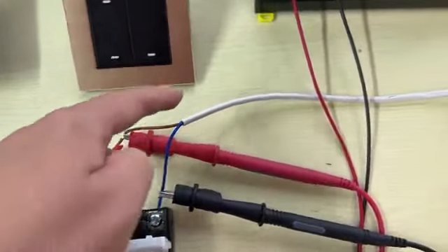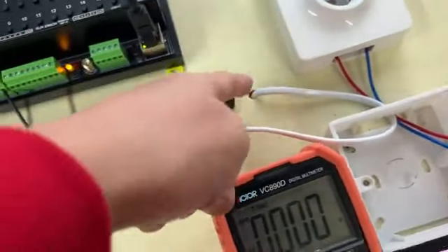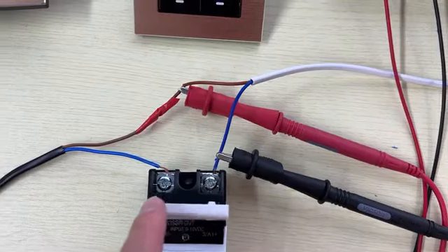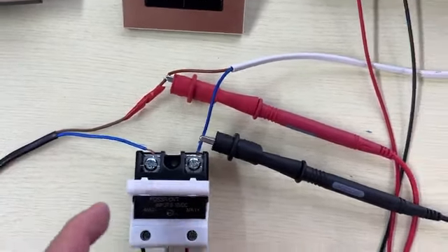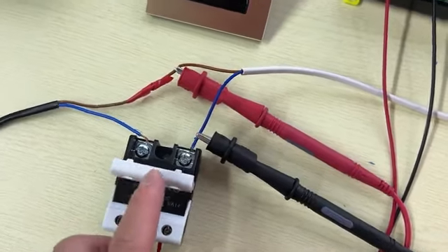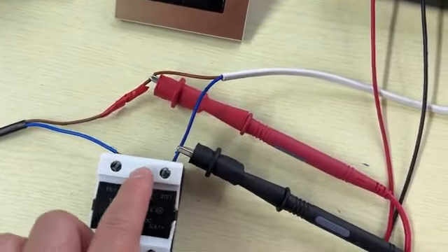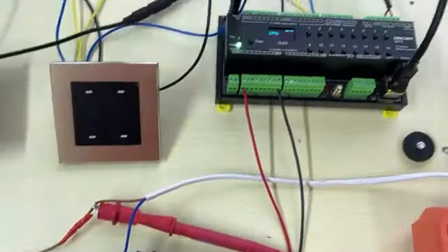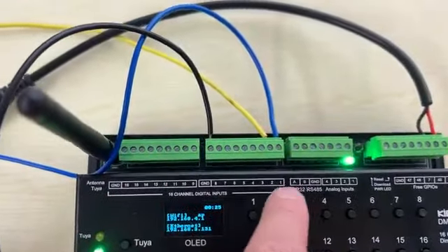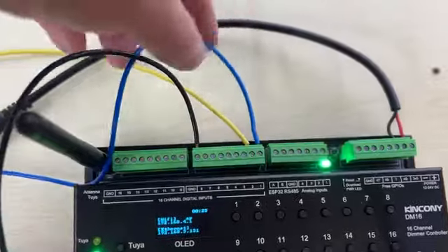The live line goes to this motor, and the motor goes back to this point, back to the neutral. So the motor and the SSR are in a series connection, and I just test the power of the motor. And this has a switch button. You can see this has 16-channel digital input. That is K1.